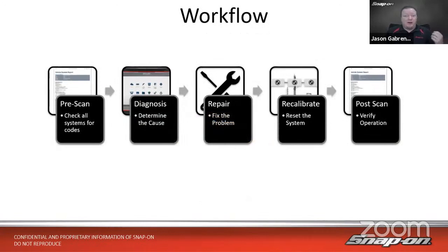Now, we talk a lot about workflow. If you've been to any of these classes, you know we talk a lot about having a good, repeatable workflow all the time. And when it comes to diagnosing, that starts with a pre-scan. We want to make sure we check all the systems for codes, right? We could have a code in another system that's not the engine that could be causing a drivability problem. We could have a code in a system that doesn't have a light on the dash associated with it either. So we want to always make sure we're doing that good pre-scan and checking all the systems for codes.